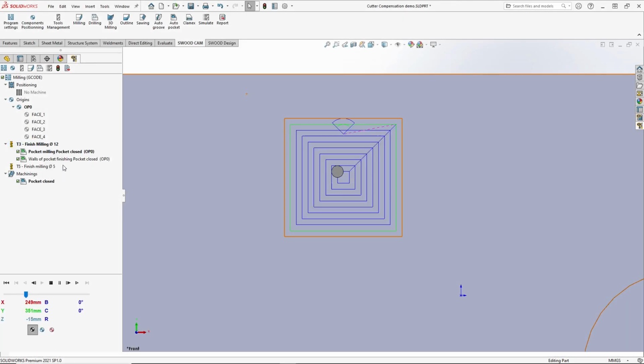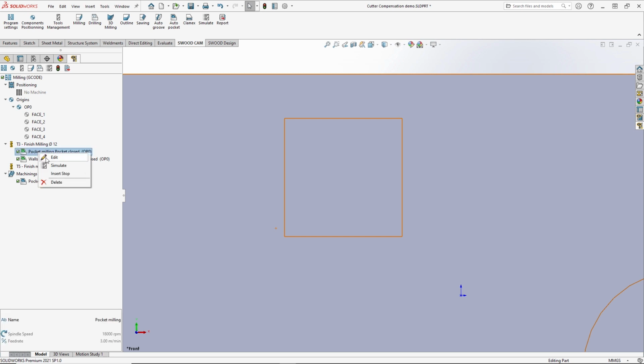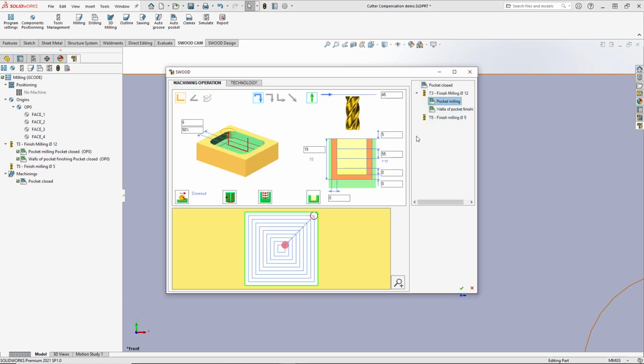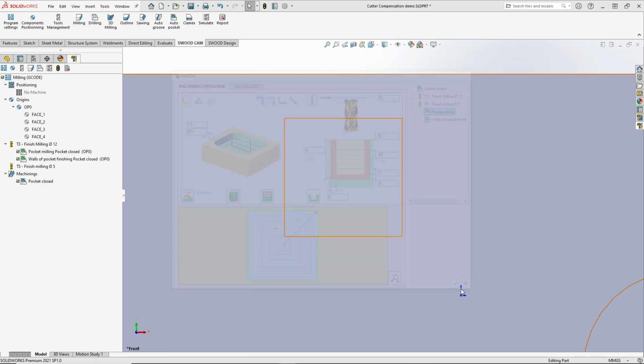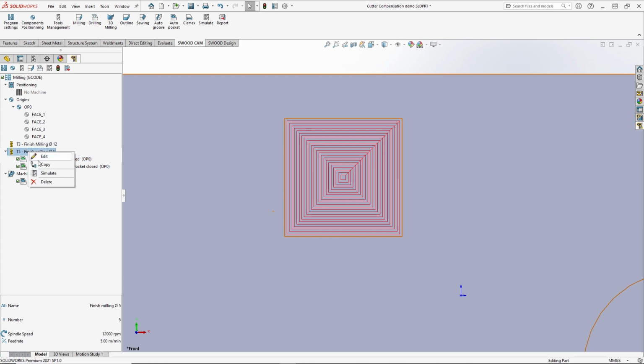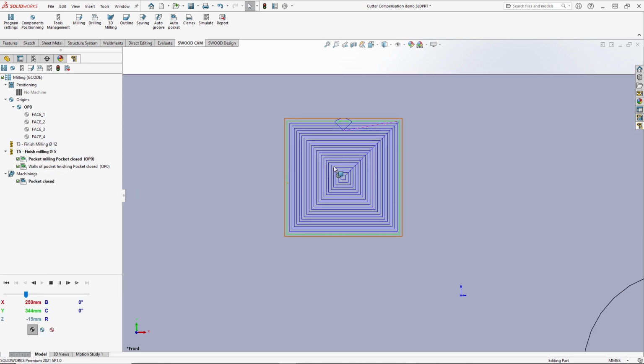An advantage of using cutter compensation is it allows the user to interchange the tool for a given toolpath without having to reconfigure the toolpath to suit the new tool geometry. Instead, the offset from the cutter compensation is in the tool and therefore it will update when changed. It can also be used in a poorly calibrated machine to quickly recalibrate the tool position without having to reorganize any tools.